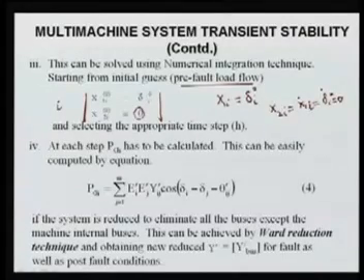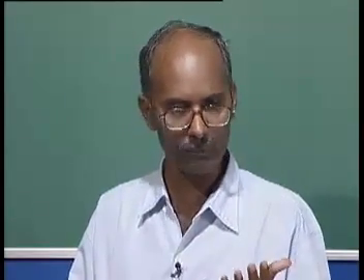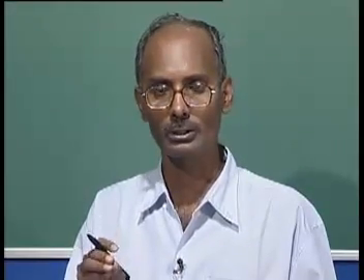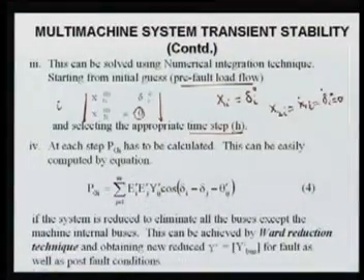At the same time, you have to select the appropriate time step of your integration. As I explained in the previous lecture, this time step is very, very important. If you choose h in a different way, your solution may be unstable, and you may get inaccurate results as well. If your step is very, very small, it may take more CPU or computational time. So you have to judge, and it depends on the system.